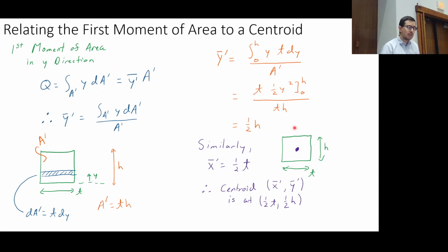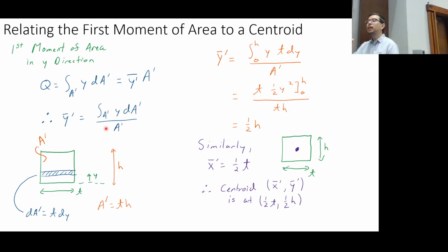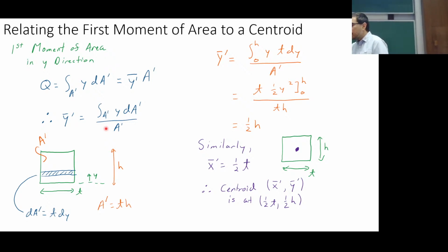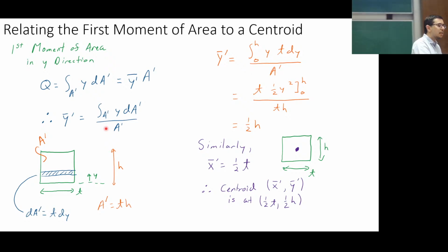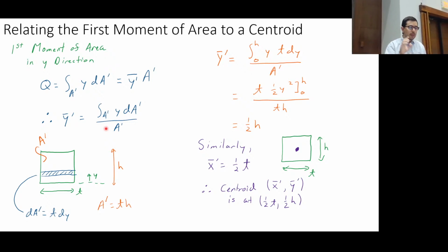The prime is just a convention that we've introduced. You could have argued that we should have used the prime when we were looking at the location for calculating bending stress as well. But y by itself is typically just a y direction. So when we say negative My over I for the bending stress, that is also a y. The y prime allows us also to distinguish the difference between y prime and y bar prime.